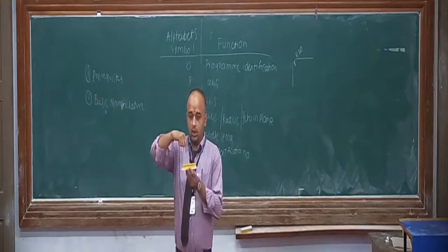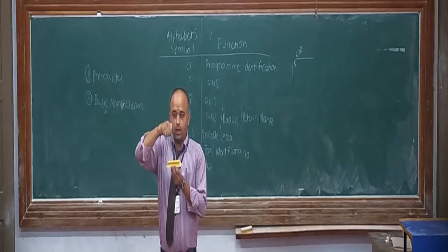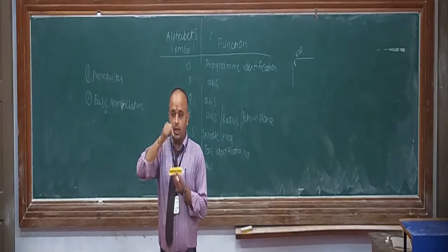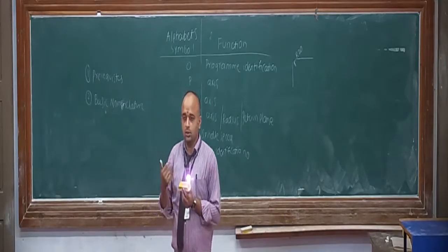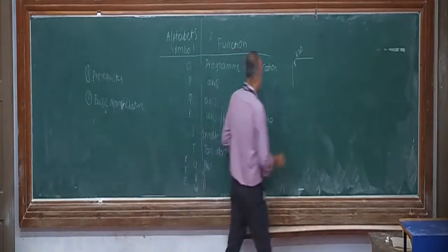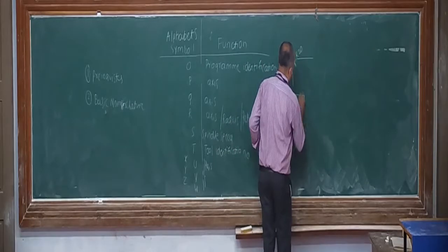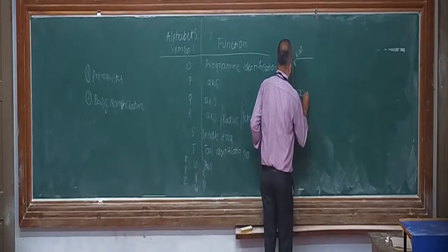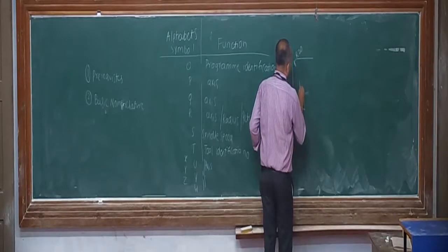So we start the drill before it touches the workpiece, and the point where it starts operating is nothing but the return plane. There is one standard, usually around 5 mm above the workpiece, where the drill starts its functioning.